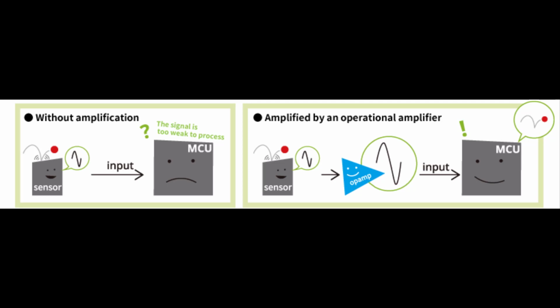In embedded systems or in electronics, we need to measure output signal of different analog devices like sensors. Sometimes the output signal from these sensors is very small, in the range of few millivolts. These output signals are not correctly measured by a microcontroller unit. So we use operational amplifier to amplify these signals and make them fall in the range of measurement of microcontroller unit, so that the microcontroller can measure the output from any analog devices accurately.